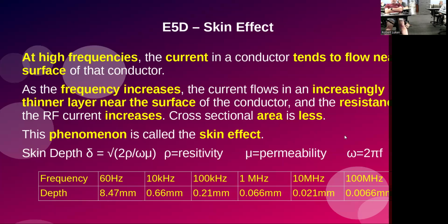That's why in a lot of high frequency equipment you'll see flat conductors that are wide, so they have a lot of surface area, or in some cases, tubular ones. You always saw those on the old tube amplifiers and transmitters to reduce the inductance. They use flat copper strap to connect from the plate to the tank circuit.